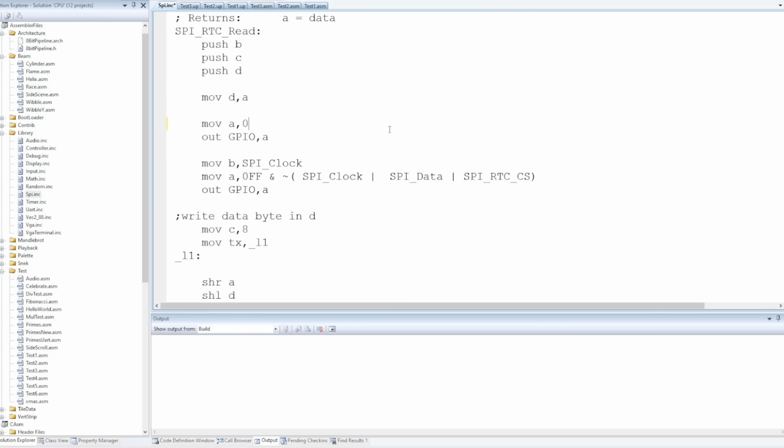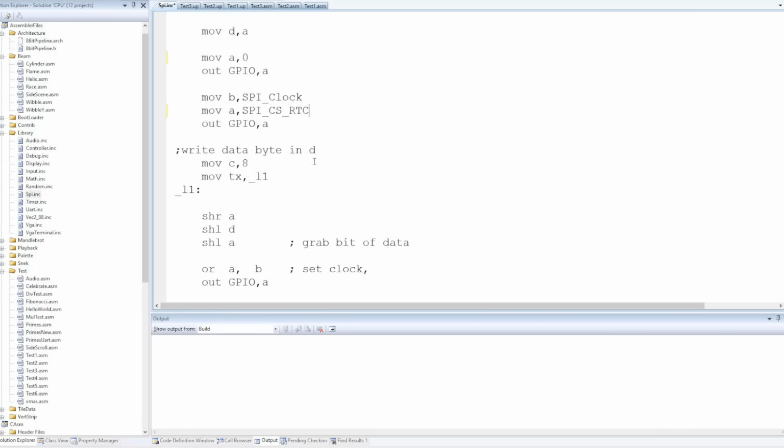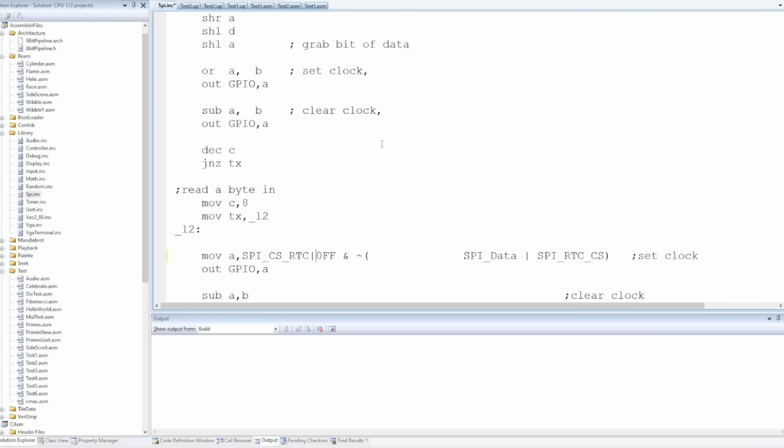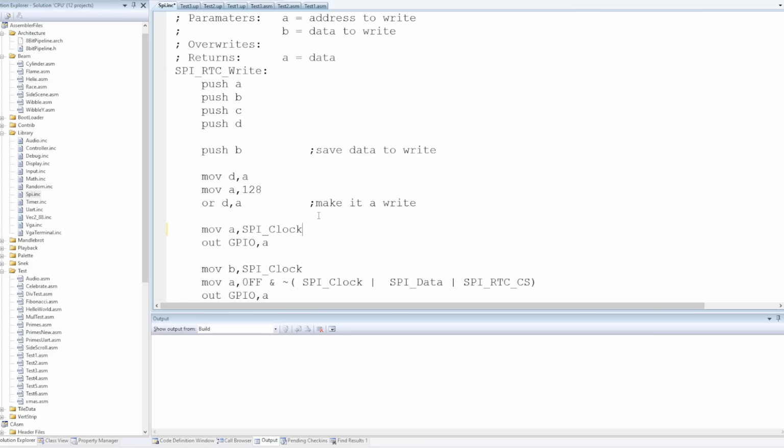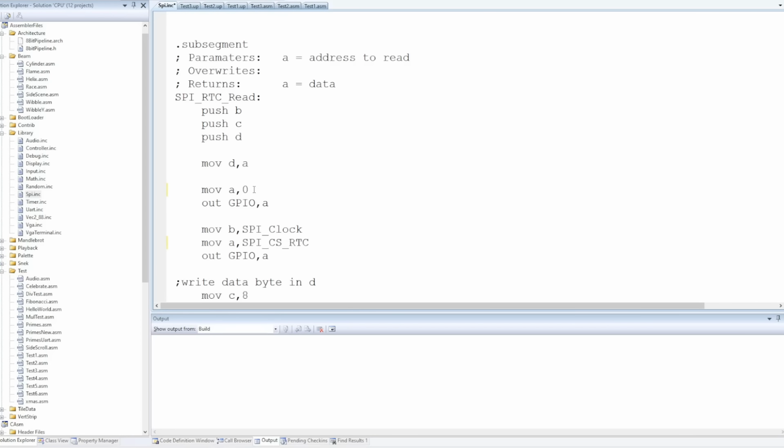Need to double check the code on those. They can't both be right, but the device is probably tolerating it. So the chip select is high and clock and data are low. That is 0. Okay, so 2 out of my 3 functions start with a high clock. So I'm guessing I just made the mistake on this one.